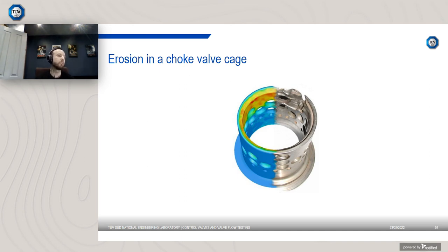So, once you combine these two tools, it can become quite a powerful sort of management tool for valves, especially if you know they're going to degrade over time. What you really want to do is estimate their effective usable life, so you can plan out shutdowns and changeouts for the component.